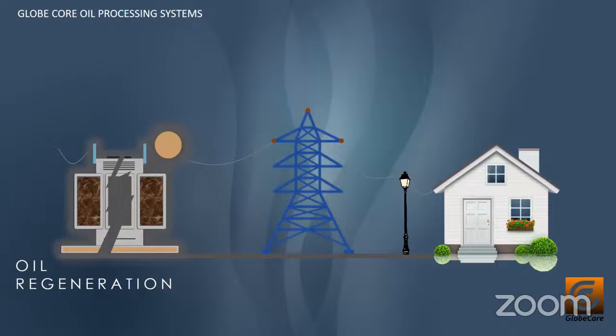As soon as the high temperature process is over and the temperature in the columns decreases, the oil enters the columns and the oil regeneration process is resumed. In the animation, we can see how oil is pumped and distributed to each of the columns with Fuller's earth.